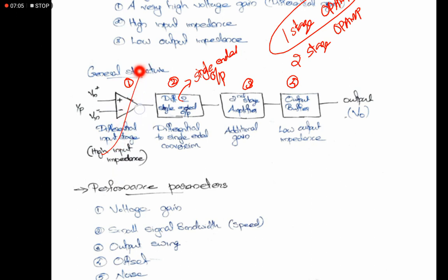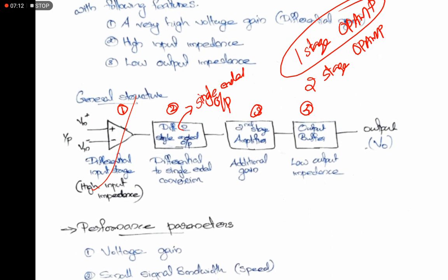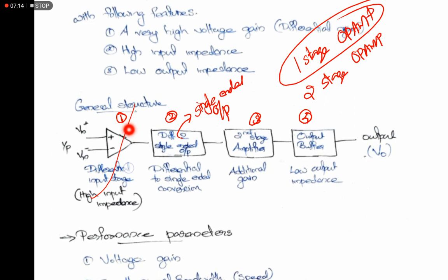So this is very crucial, and this will be designed based on low noise amplification, and we will consider many design criteria for designing this one. From this one we will take a two-sided output that will reduce the effect of accumulation of DC in the propagation. The second stage is also a differential amplifier, because from here we are taking a two-sided output. Here also we are using a differential amplifier, and the output of this differential amplifier is a single-ended output.